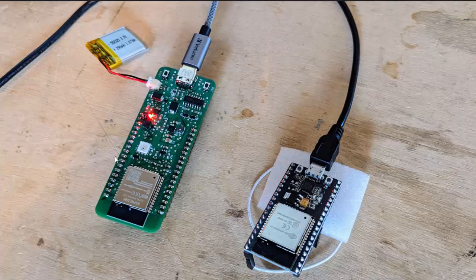Now they're going to communicate back and forth. In my simple program, the way you communicate using ESP-Now is, for the primary board to talk to the secondary board, we have to know the secondary board's MAC address. So in our simple example, the secondary board is going to print out its MAC address to the serial monitor. The primary board is going to ask for a MAC address to be entered in its serial monitor. We're going to enter the secondary's address in the serial monitor. Then the primary is going to talk to the secondary and send the secondary its MAC address, so that the secondary can talk back to the primary. I hope that makes sense. That's what we're going to show in our basic example.